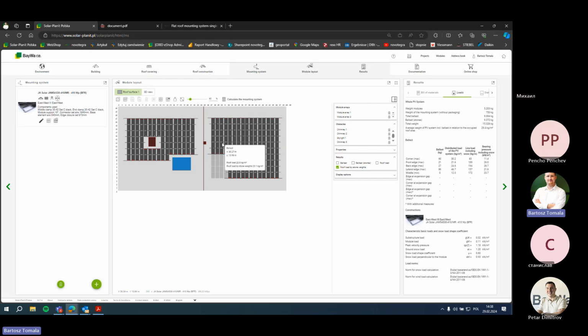construction and the way to mount it are different, because all this construction is already prefabricated, let's say. You don't need anything. You don't even require a saw to make this construction. You just need to fix the clamps on the rails. Of course, the modules have to be clamped, so the only tool you will need to make this whole construction is just one key with M8.